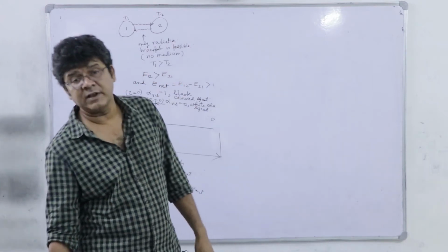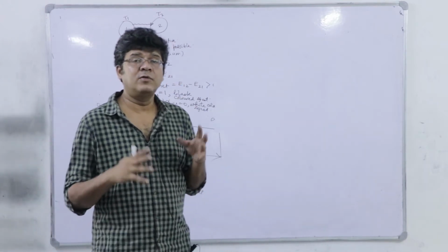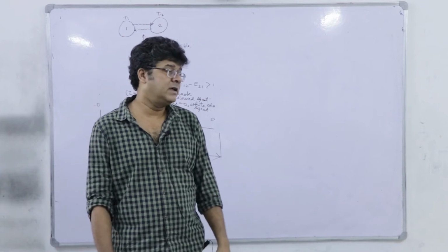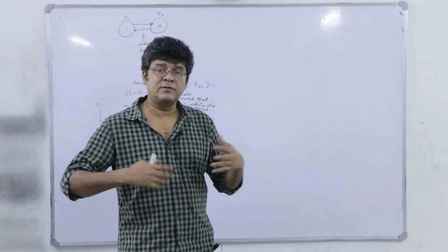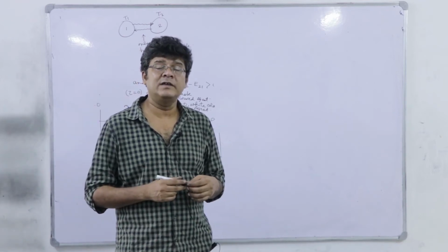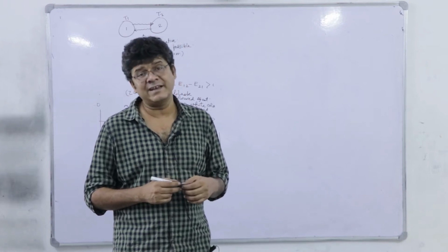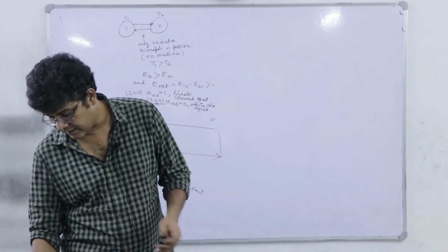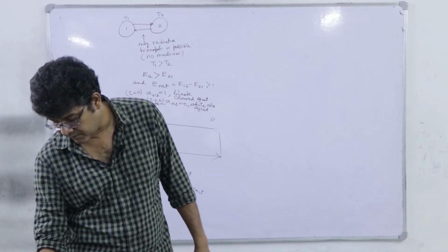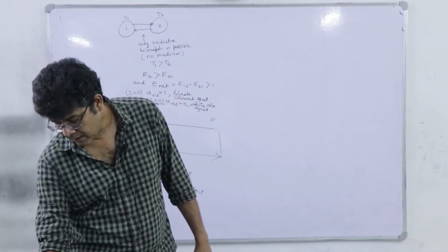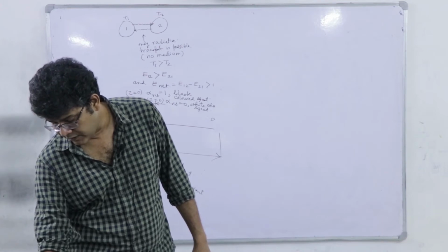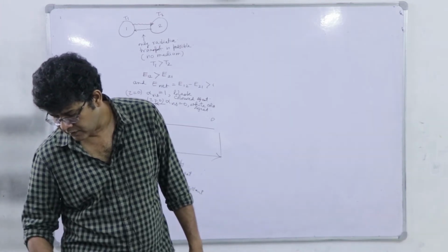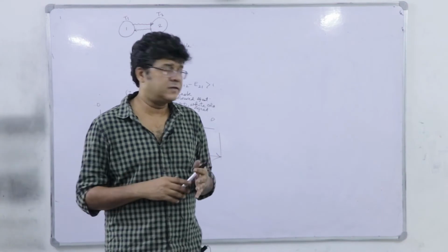And another property which is very important, and we will actually explore that property, that radiative property or absorptive property of a black body is independent of direction, right. So, it is not a spectral object, it is rather a diffuse object, perfectly diffuse object. Like emission of a black body occurs in all possible directions, right, and also the absorptions.